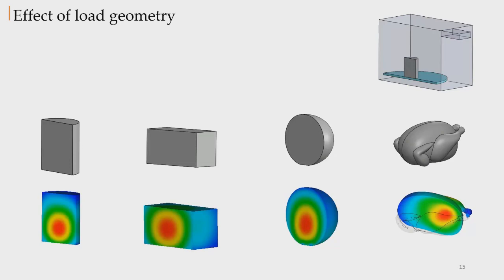As we can see from the heating profile, all load shapes have the same temperature distribution since we didn't change the material, with the maximum heat increasing from the center to the outside. This behavior describes well the dielectric heating, in which the heat is dissipated inside the irradiated sample and transfers from the medium to the outside.